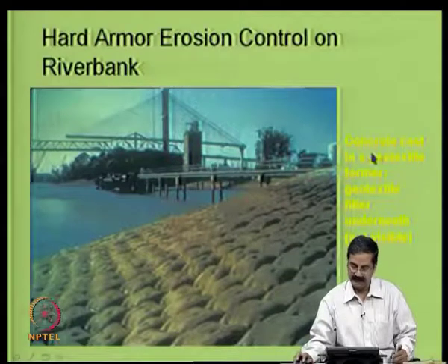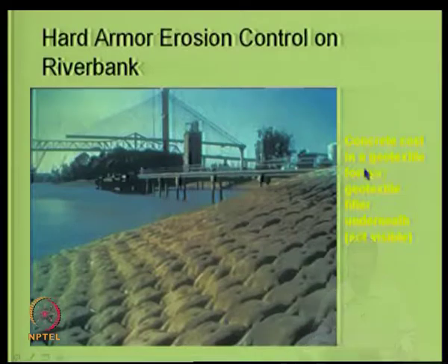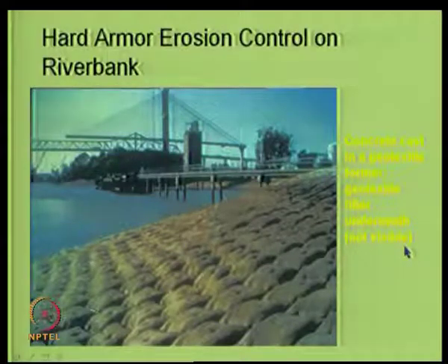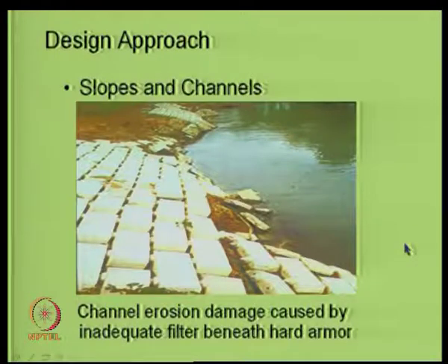In fact, say this is concrete cast in a geotextile form, and a geotextile filter is provided, of course, it is not visible. Some of these measures use the concept of geotextile bags, instead of stone pitching. Stones are okay, but you can also design geotextile bags: put a lot of sand into the bag, a small containment system, and place it here like that.